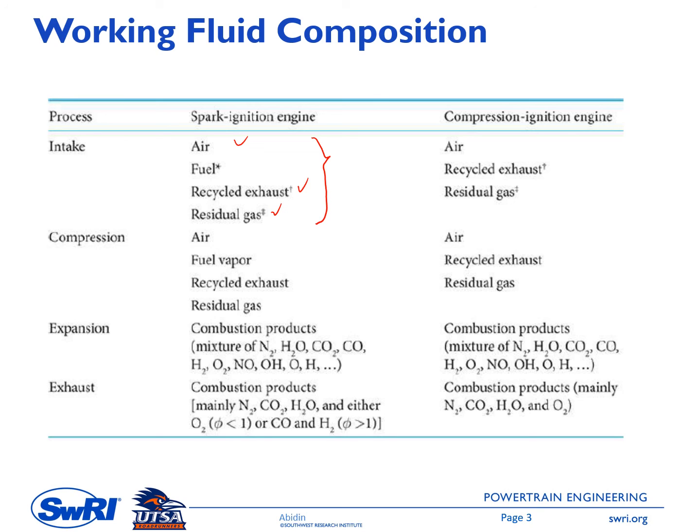If we have GDI, then in the intake stroke we don't have fuel. So in the intake stroke we might have air plus recycled exhaust, if any, or it only contains air and residual gas. On the next column, what is the composition inside the diesel engine during the intake stroke?